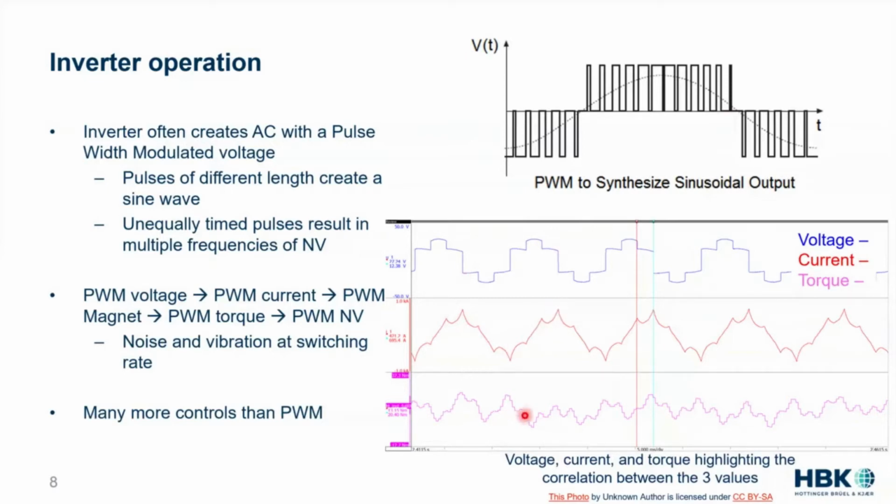And then in the pink, I have my torque. And granted, this is one of three phases, so this torque's going to have a higher frequency torque ripple than we see here. But we can see while that switches on in blue, we have this current that's dipping and rising, and we have a torque that's subsequently rising. And these are all things in torque that are going to excite the housing. So this really is a large electromechanical problem. And each control type is going to have its own kind of torque characteristic and its own noise and vibration characteristic because of where that excitation is going.